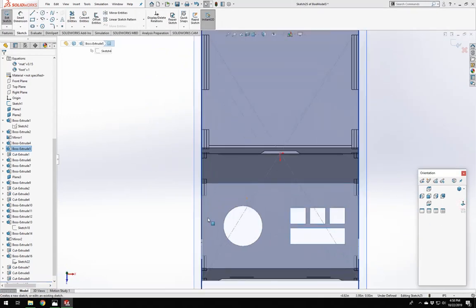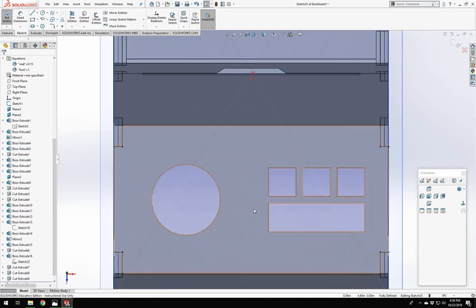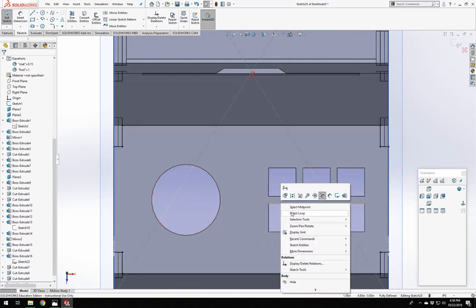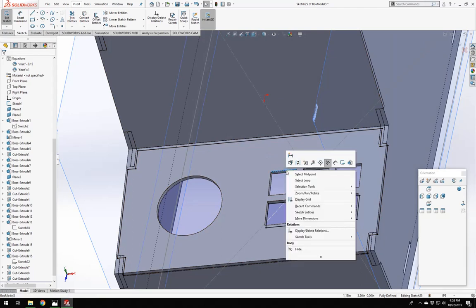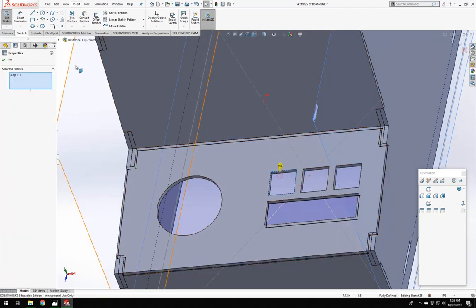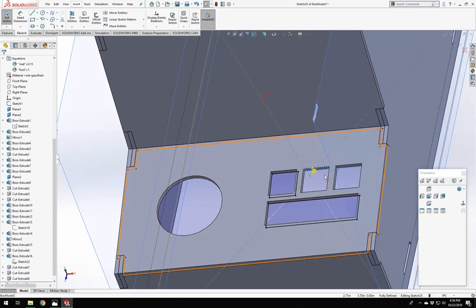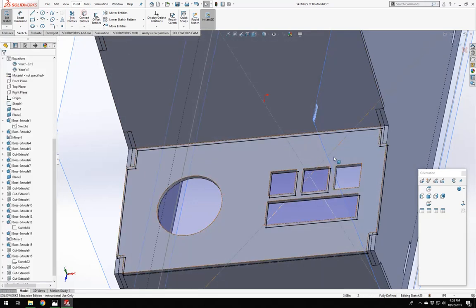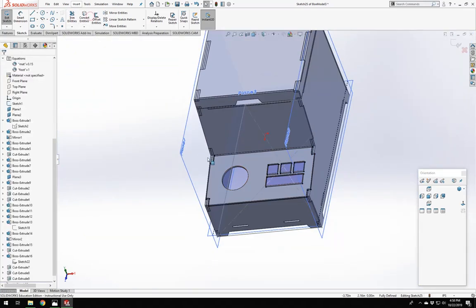Now this layer is almost identical. So we're going to convert the entities. We're also going to convert the buttons. And an easy way to do that is we can select a loop and convert. Same thing. So we just select the edge, flip which loop basically we're after. There we go. So there are our buttons.